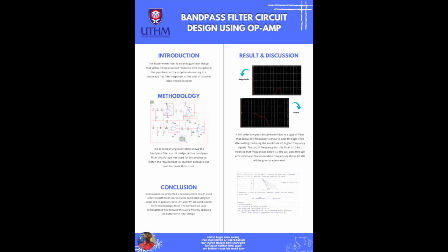In order to calculate the values for the high pass filter, we use the formula R = K·M over D_k, where M is the magnitude coefficient, which is 1720.594, while fc is 9.75 kHz, C is 0.01 microfarad, as I mentioned just now, while D_k is the fifth order normalized capacitor value, which is referred to in the table that I already attached in the report.